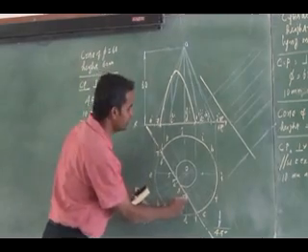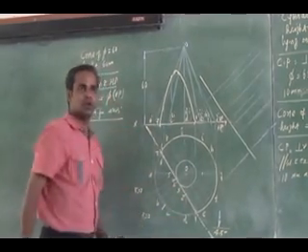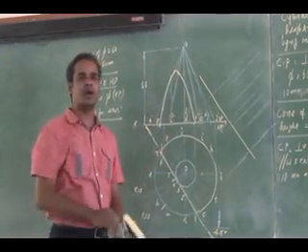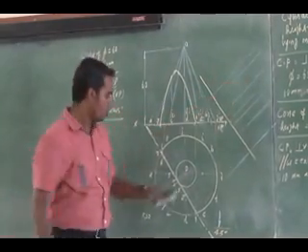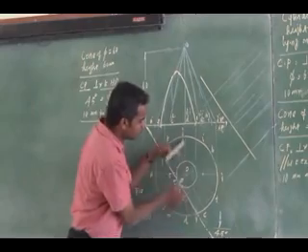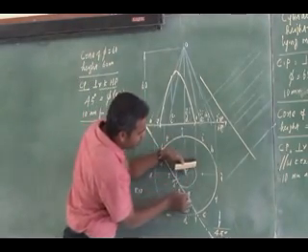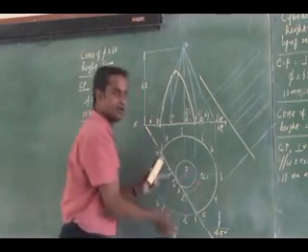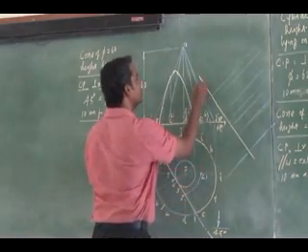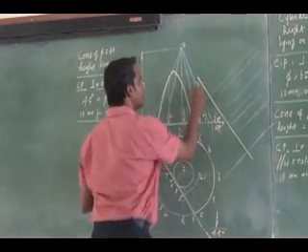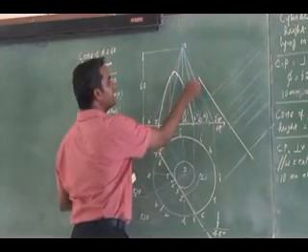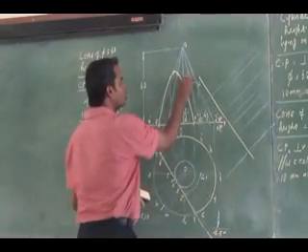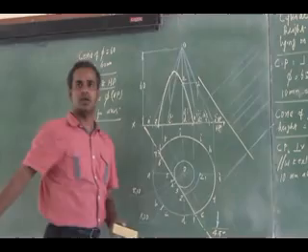Then cutting point 2. You see, cutting point 2 is on D. OD is a vertical generator. How do I have to project the cutting point? Similar to the previous problem, cutting point 2 is on OD. This cutting point 2 distance has to be rotated to an extreme generator, OG. So my 2, 1 should be projected to the OG here. Then it is horizontally transferred to OD. So this is going to be my cutting point 2 on exactly OD.